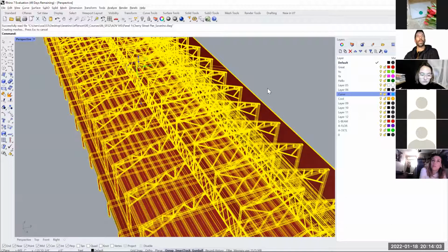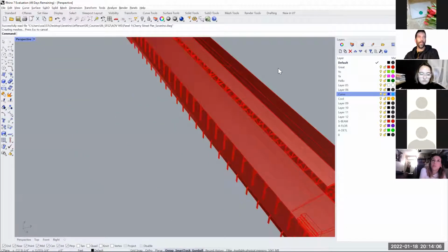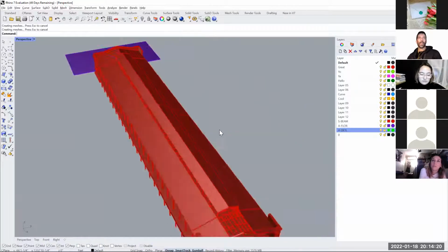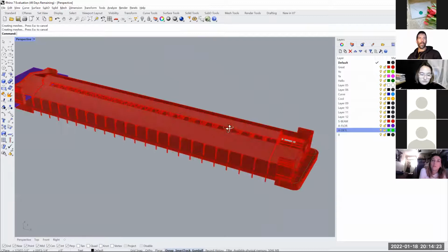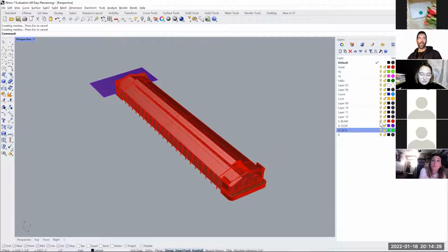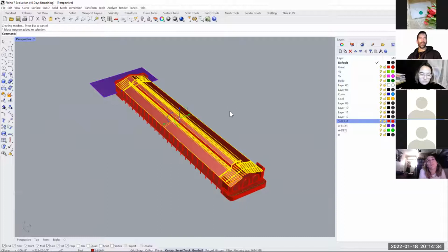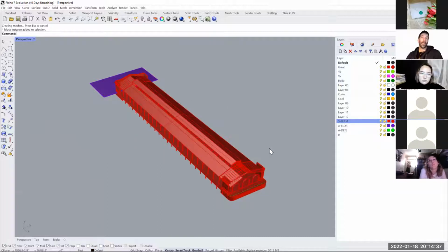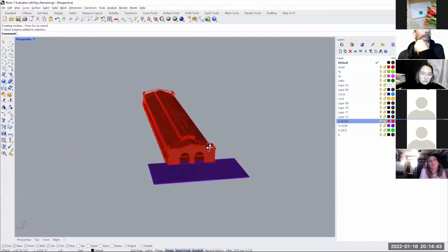There you go. When you bring an AutoCAD file from Revit, all of the Revit files, when you export them as DWG, they come with layers and they tend to look like these ones here. Beam, floor, and so on. Those are basically Revit elements. So now that you're in Rhino, it's tricky in the beginning because you move with completely different buttons, but you have your model and each of them will have a different color. Right now, for example, there are too many things with the same name. Ideally we would clean the layers a little bit, but if you bring them from Revit, it should look quite okay and nice.